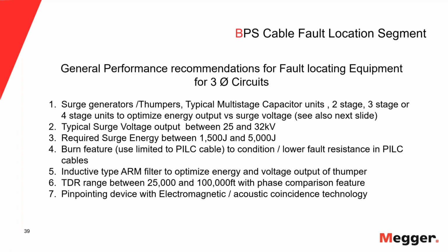But if you really look at it, that current is nothing compared to the normal operating current on these cables, okay? So the current itself cannot damage the conductor. But when you have a low resistance fault, it will do a lot of damage there, okay? And that's the whole intention. It should condition the fault so I can thump it, okay?